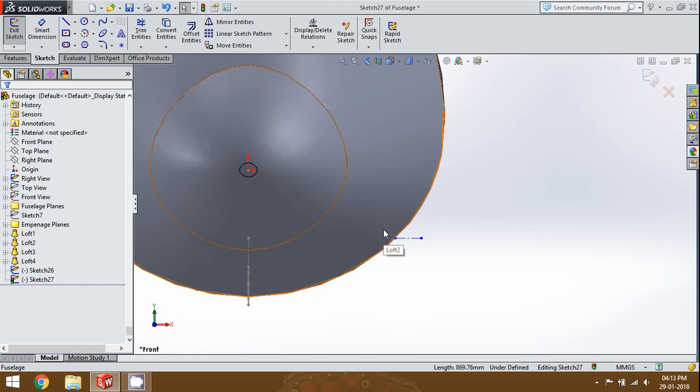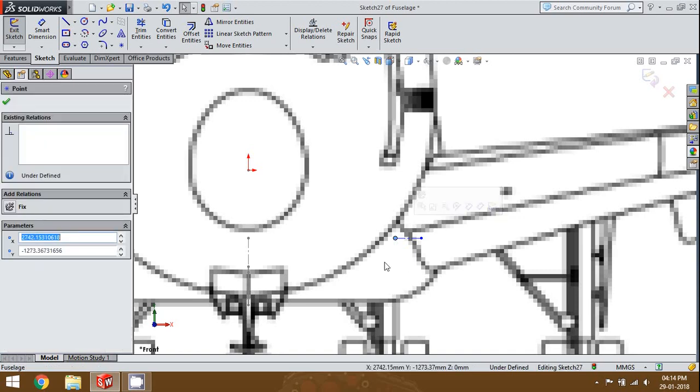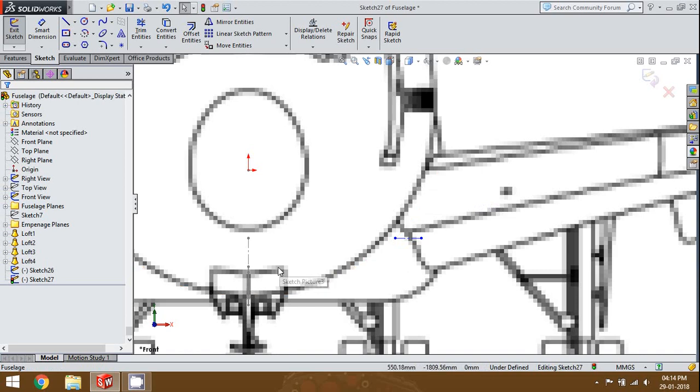So in this belly section, we're not going to use traditional 2D guide curves. We're going to use a 3D guide curve, just like the way we used the 3D guide curve for the empennage section. So now we have to pop the front view image back on. So see on the sketch, the fuselage starts from there, but on our aircraft model that we made, the fuselage starts over there. So that's why I asked you to convert the entities from the model itself.